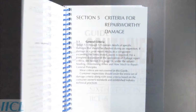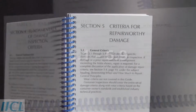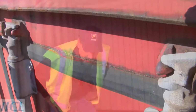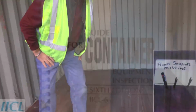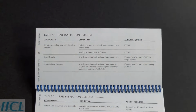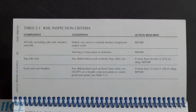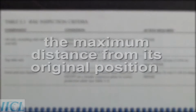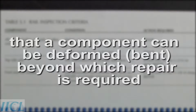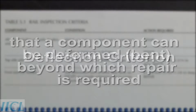Tables 5.1 through 5.9 in Section 5 of the guide list the inspection criteria. With the exception of a general rule that cut, cracked, or broken components and missing components are unacceptable, the majority of the criteria are listed as dimensional limits. The dimensional limits are used in one of two ways. The most common way is as the maximum distance from its original position that a component can be deformed, or bent, beyond which repair is required, called a deflection criterion.